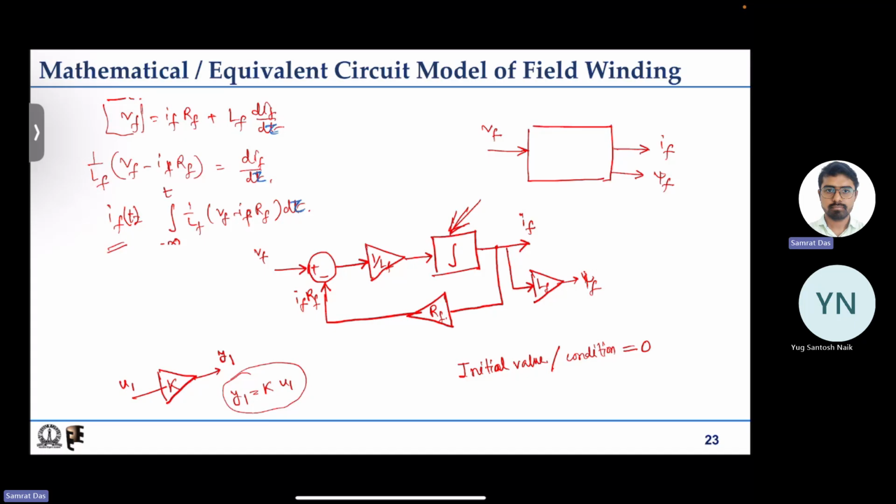Or you can also do that by writing equations, and this integration and other things can be done in a discrete fashion using numerical techniques such as forward Euler, backward Euler, trapezoidal integration. All those things you can do. Basically, Simulink is doing some numerical integration to solve for whatever you are doing. You can also define that yourself and write your own thing.